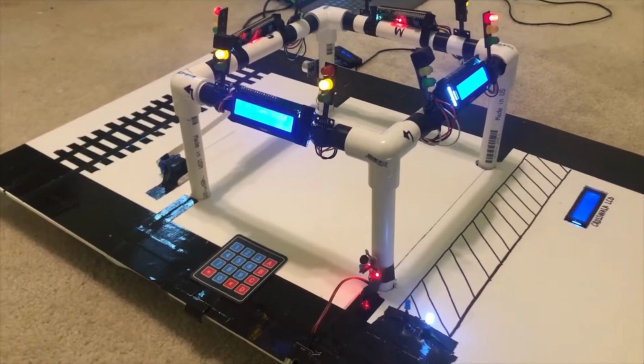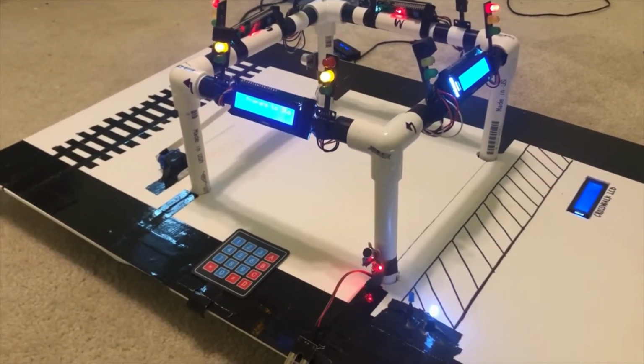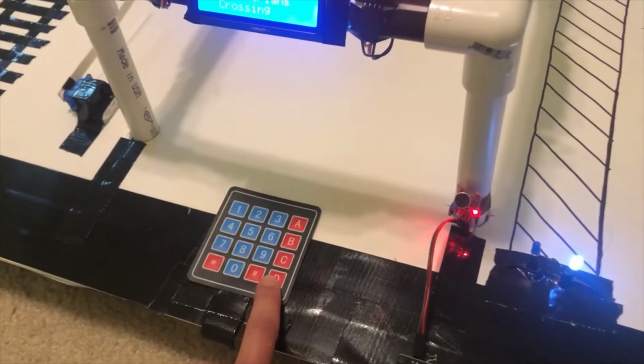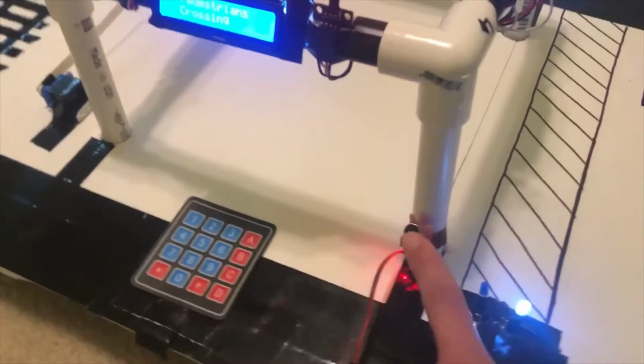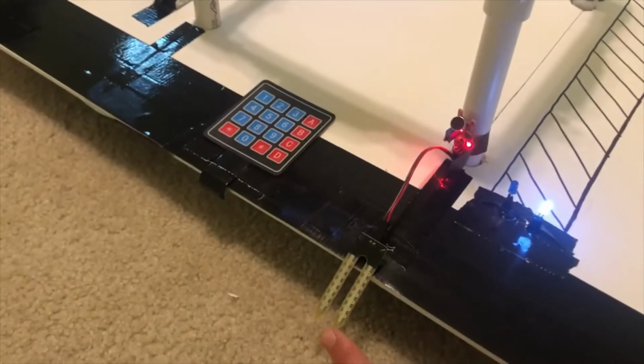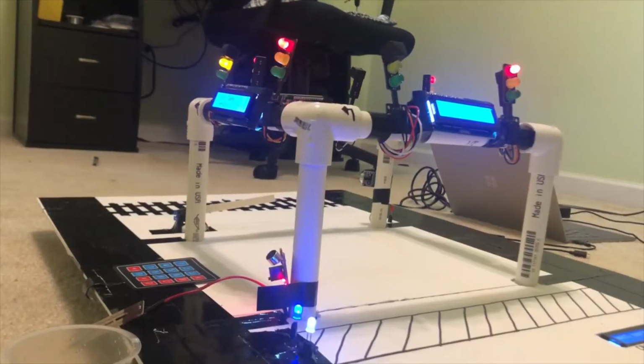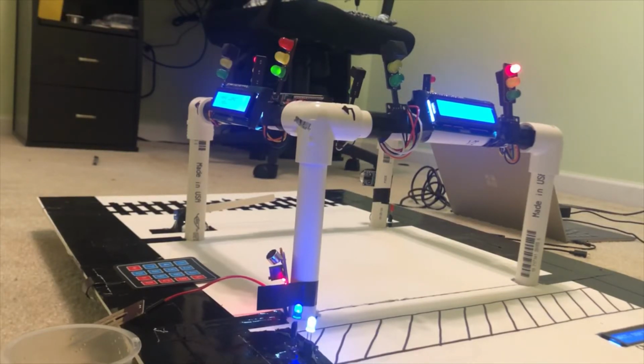While the emergency mode and the flash flood mode can be activated using the keypad, C for emergency, D for flash flood, they can also be activated using the sound sensor and the moisture level sensor. So I will go ahead and demonstrate those. Notice that the white LED at the bottom of the screen is on, and when the sound sensor goes off, it will go off as well.